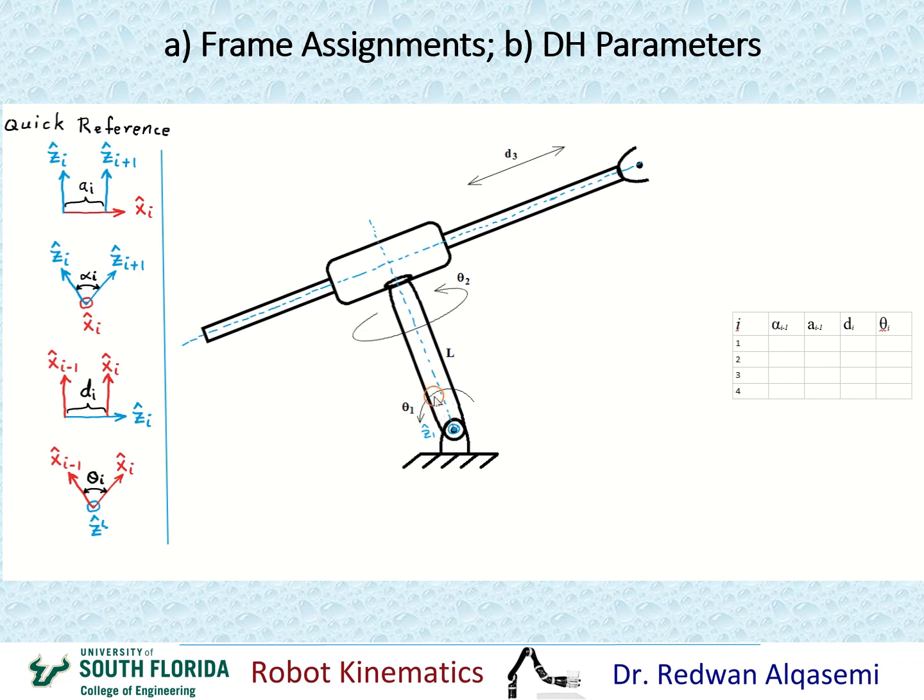Now for the second axis of motion, I have this as joint 2 right here. It rotates about this axis right here. So this is my axis for joint 2. I'm going to draw a line from here upwards, and that would be my joint 2 axis. I'm going to call this Z2. Now my third joint is a prismatic joint.